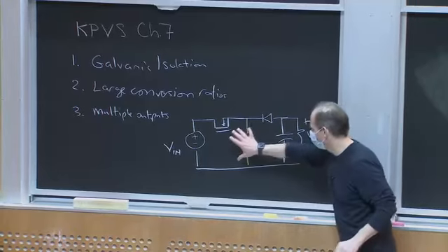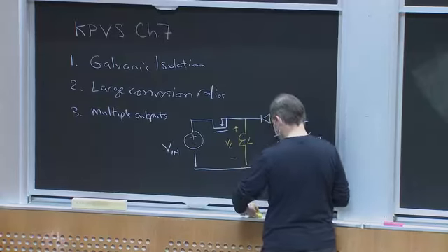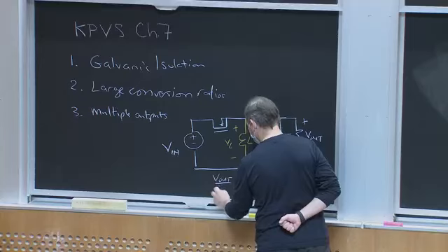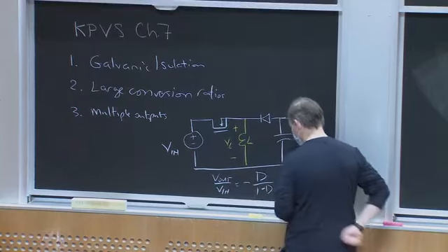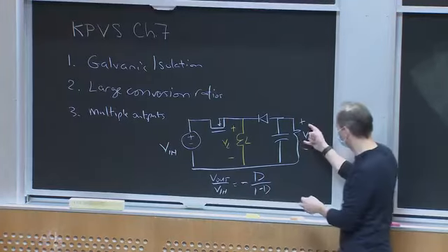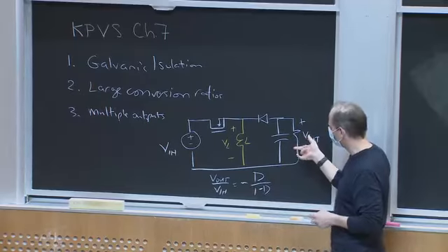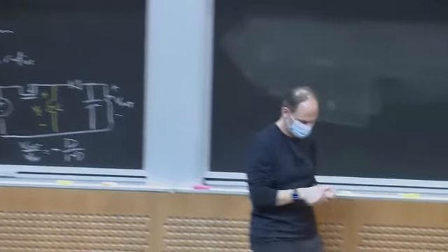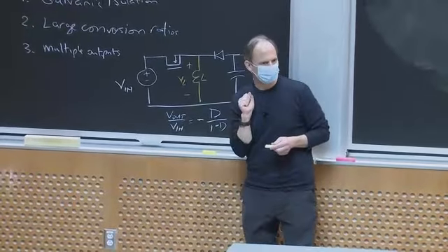And we said if I analyze this converter, the voltage across the inductor L, V sub L, has to have a 0 average balance, and what we get from that is that Vout over Vin is equal to minus D over 1 minus D. Okay, so it has a negative gain, the output voltage is negative if the input is positive, and I can make the output voltage smaller or larger in magnitude than the input based on how I select my duty ratio. Okay? So, I have this sort of AC waveform at VL in the middle of my circuit, right?